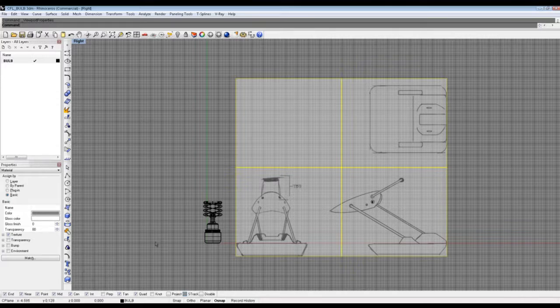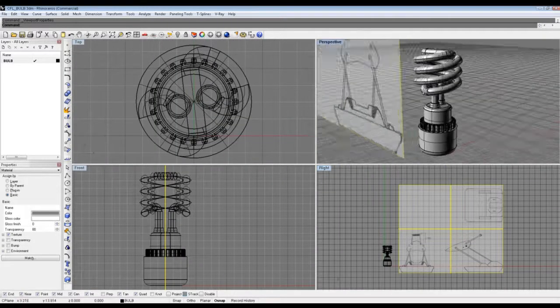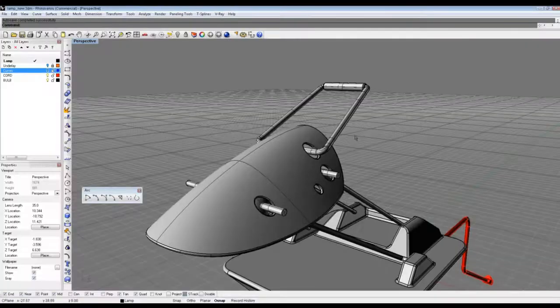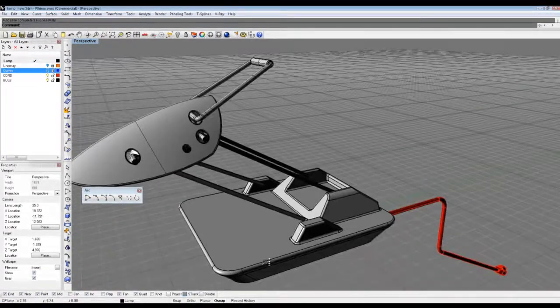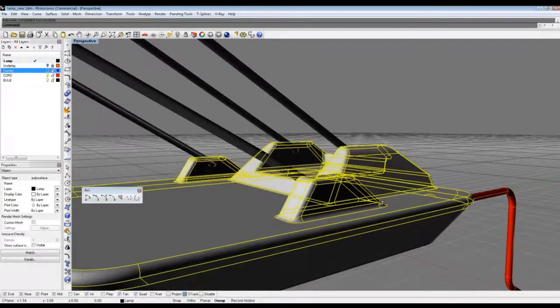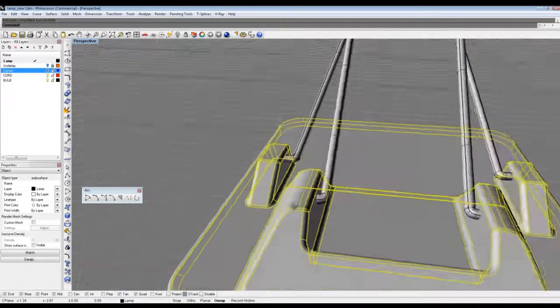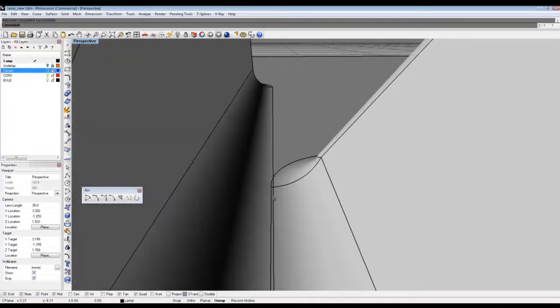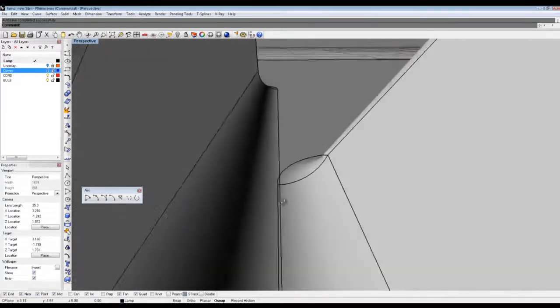if he wants us to be able to see how you repair the surface continuity, because we all run into the fillet problems. Oh, that's a good question. So, oftentimes what'll happen is, let's get out of here and go back into our lamp. So part of this filleted poly surface here is actually broken, and it doesn't look like it, but if I zoom in really quick to this area here, you can see this is like the prototypical issue with fillets.